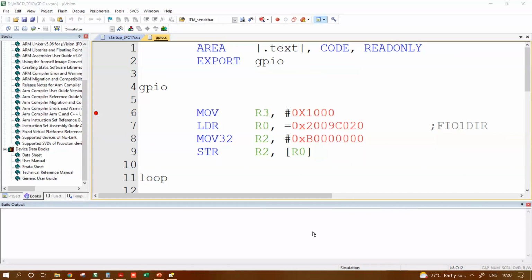Does debug printf work in the simulator? No. Debug printf is actually with your hardware. Yeah, could be a virtual serial port. What do you mean by virtual serial port here? If you want, you can see the printf information in simulation, because there is no hardware and no problem or danger of using the UART there, since it's a virtual simulation. You can see printf information in the simulator. That's possible.